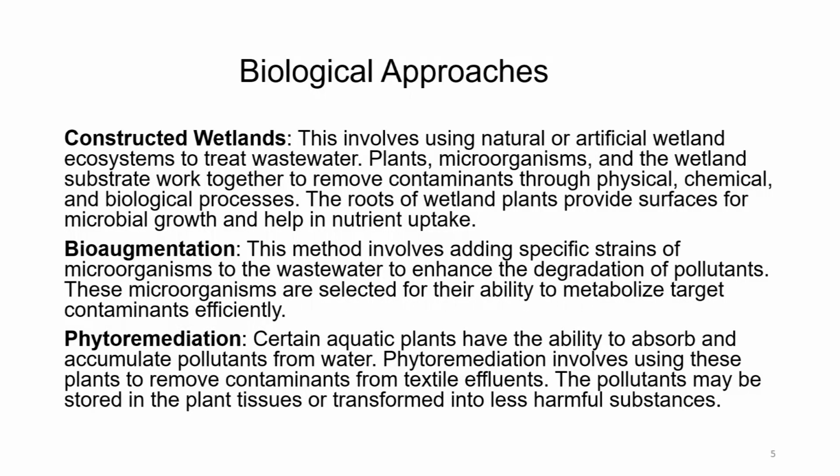Bio-augmentation. This method we had not discussed, so this is a new idea which you have to understand in this lecture. This method involves adding specific strains of microorganisms to the wastewater to enhance the degradation of pollutants.